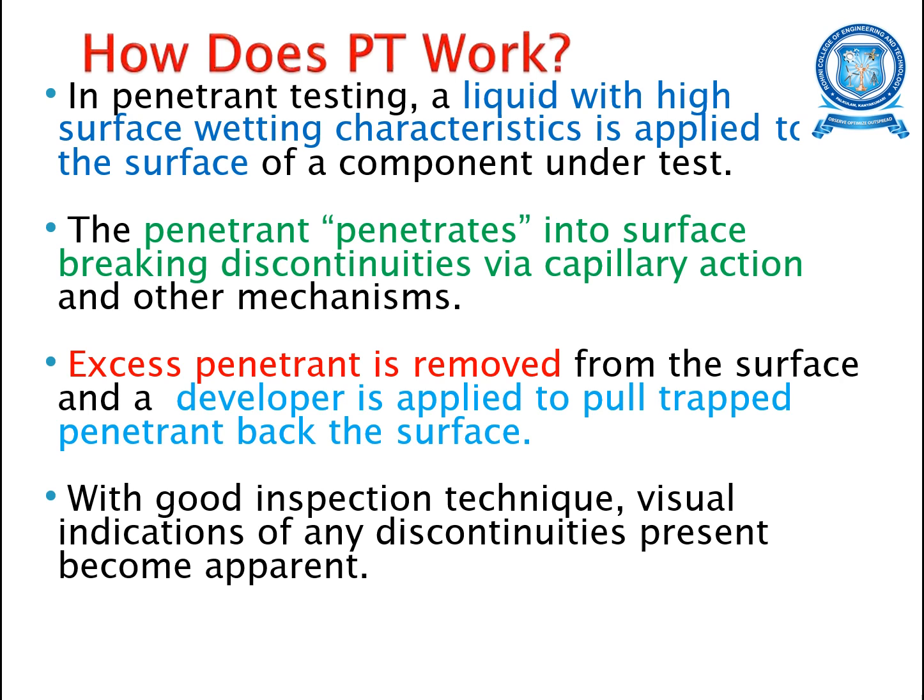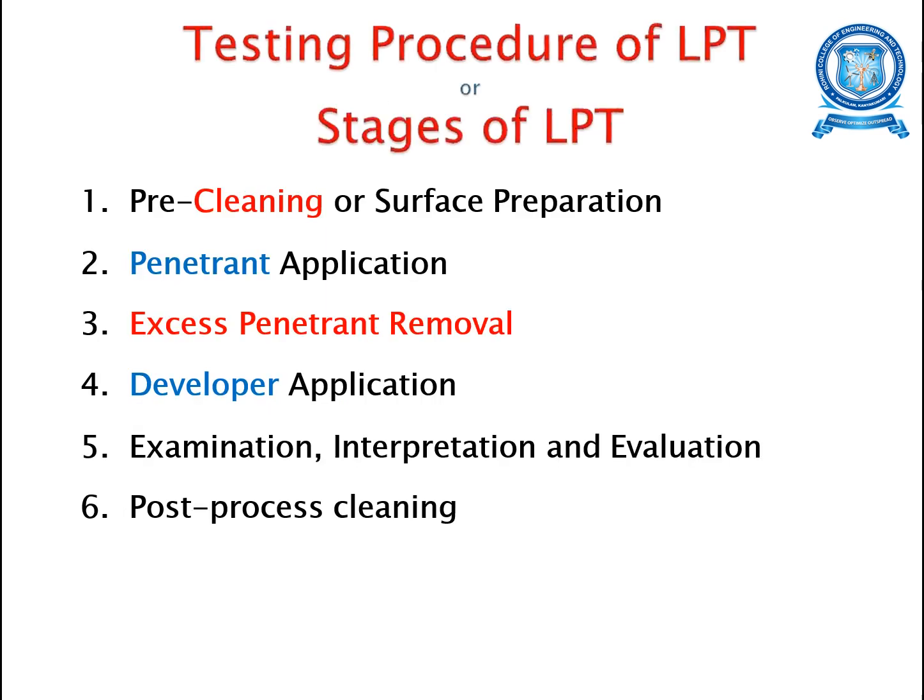And the excess penetrant is to be removed from the surface, and then a developer is applied which will pull out the penetrant back to the surface. So with good inspection techniques, visual indications of any discontinuities present become apparent.